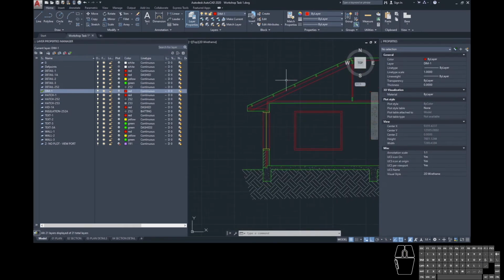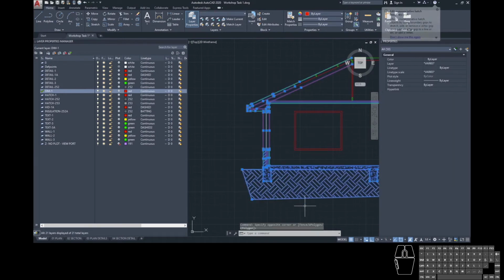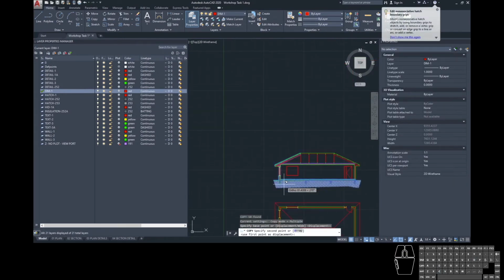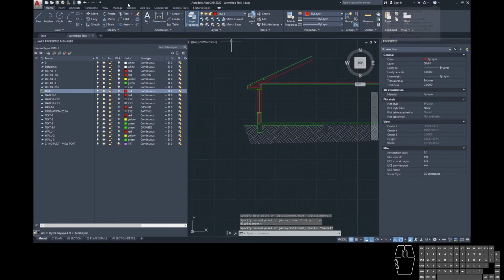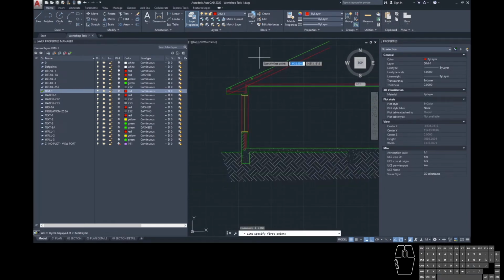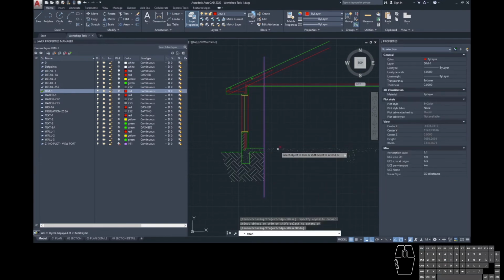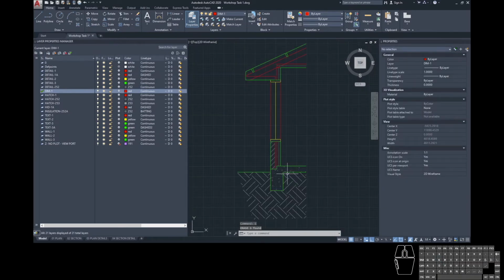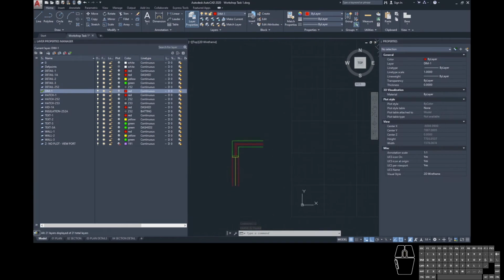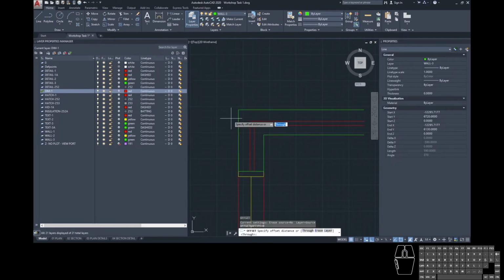I'm going to do the same thing with this part of my section. Pull this across. I'm going to come in with the line tool and just trim this down. So I now have the base for each of my details here. So obviously I'm going to need to start drawing in each individual brick. So again, I can just start to use the offset tool to do that.